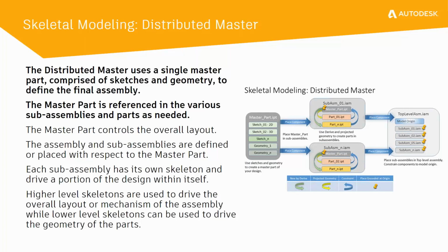So the difference from a single part to distributed master is that the subassemblies are referencing directly to this master part rather than referencing through the top level assembly. And these subassemblies then are transferred through to the top level assembly.